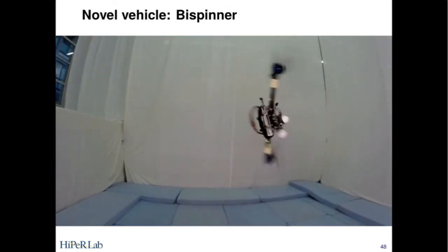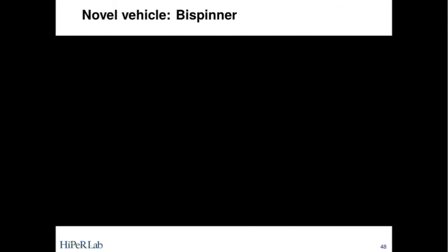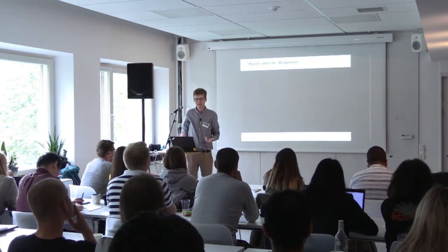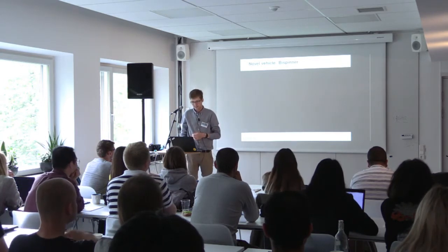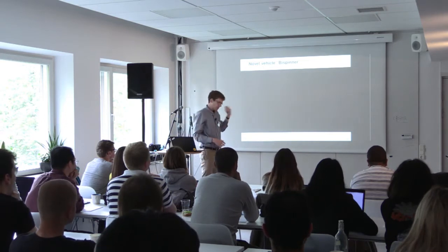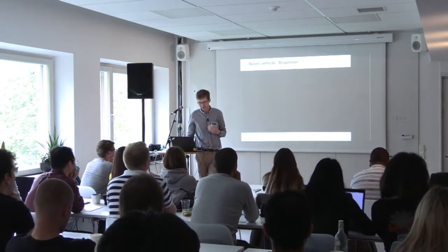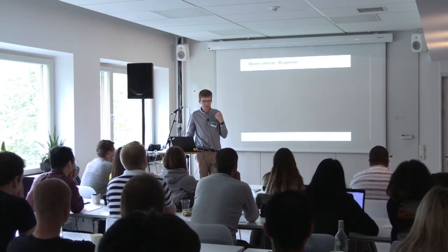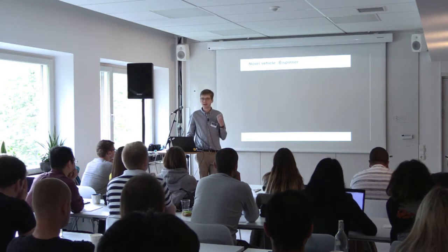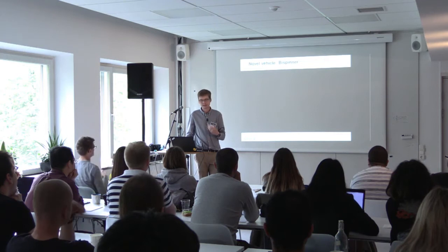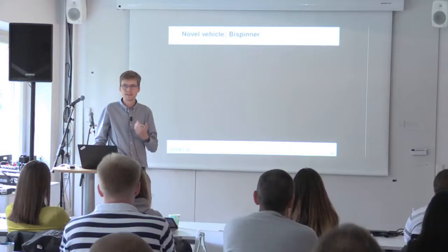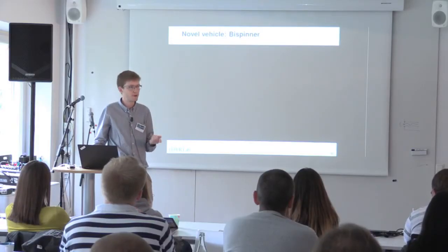Okay, so what do we notice here? We notice that there's this extremely rapid transition from controlled flight to this flip over failure where the vehicle then crashes. And this was instructive for us being naively just trying things and hacking around, because it showed that even though this vehicle is theoretically capable of flying, it was very sensitive to disturbances, right? So if you did the analysis, this is a controllable system, and it should work, and it does work, but the ability to reject noise inputs, to reject these disturbances, was extremely poor.